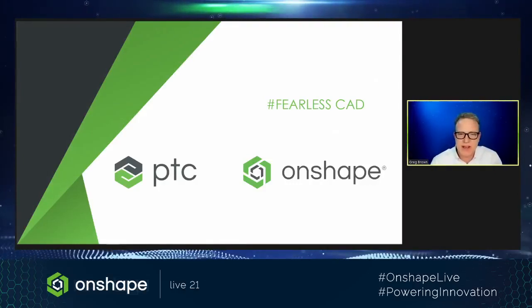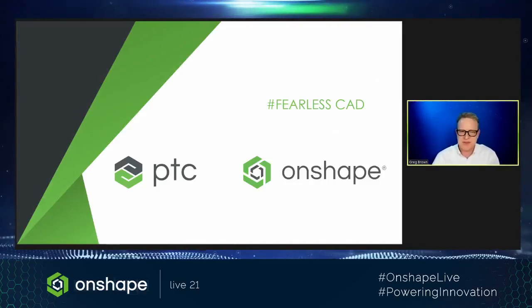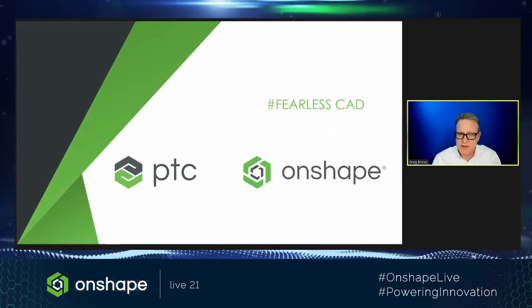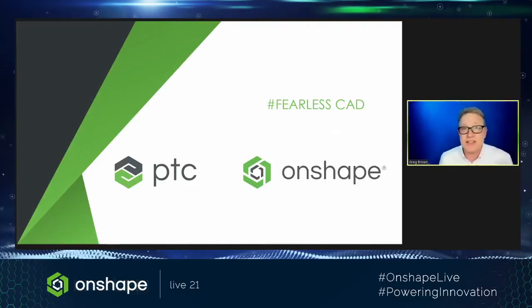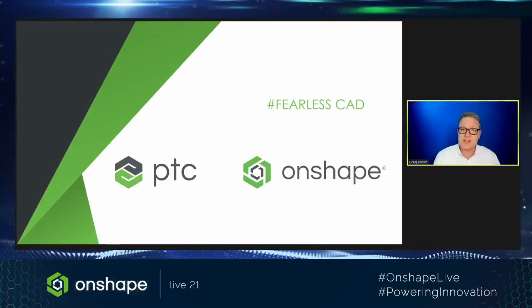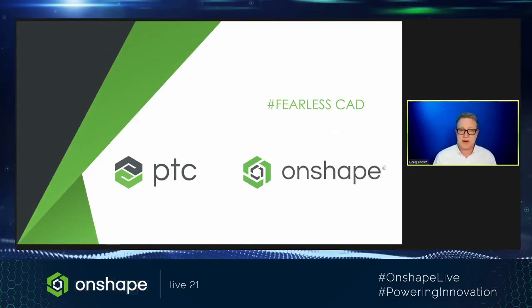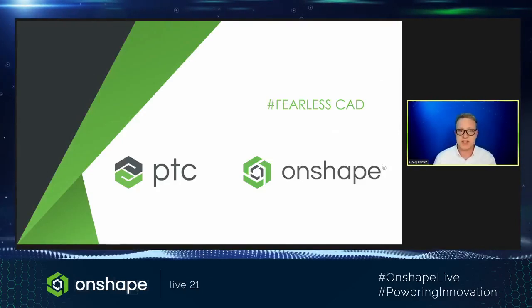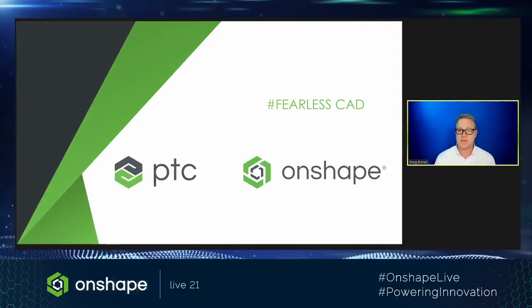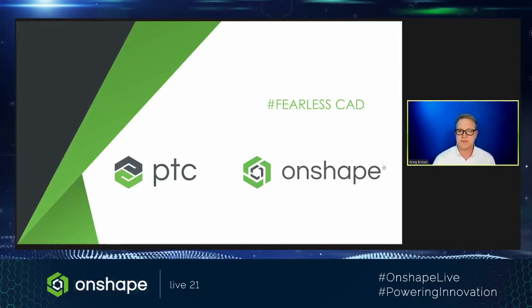Does Onshape have any surface modeling tools? Old CAD has an entire menu of surface modeling tools with equivalent commands in solid modeling. I can't seem to find these in Onshape. Yes, in fact, Onshape does have these surface modeling tools. It's just that you might not have seen them because they're combined with the solid modeling tools. So everything like an extrude or a sweep or a loft will have a solid or a surface feature option right there in the same dialog box. Just look in the dialog, you'll see that there. And you'll see some of the options will change when you choose the surface option.